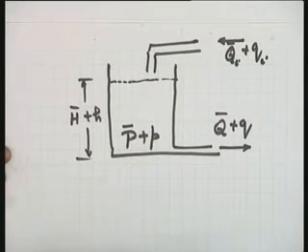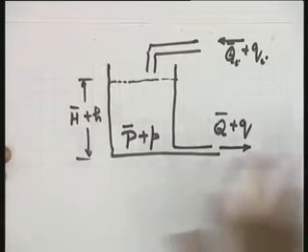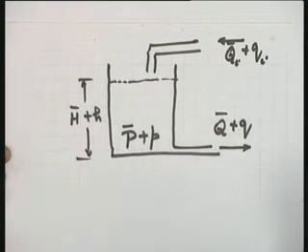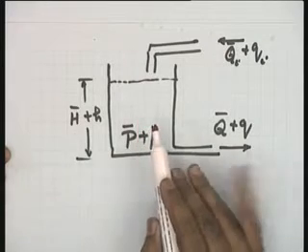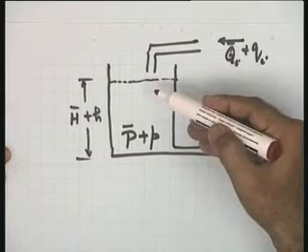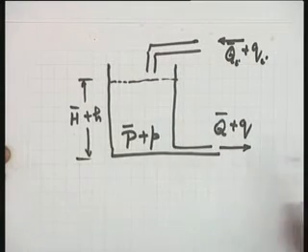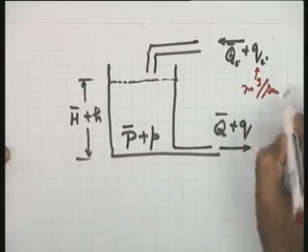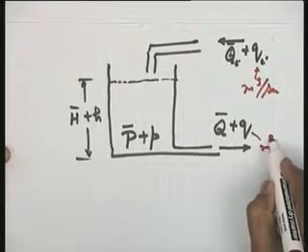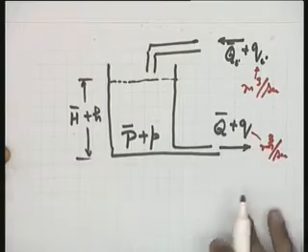In this case, I will put it this way. I will write the volume balance equations, assuming that density throughout remains the same. So I can take up volume balance equations for this system, and therefore the rate of change of volume of the liquid in the tank is equal to the rate of change of volume entering the tank minus the rate of change of volume leaving the tank. That becomes my basic equation. Okay. So let me say that this Qi is meter cube per second. It is the rate of change of volume entering the tank. Q is in meter cube per second.